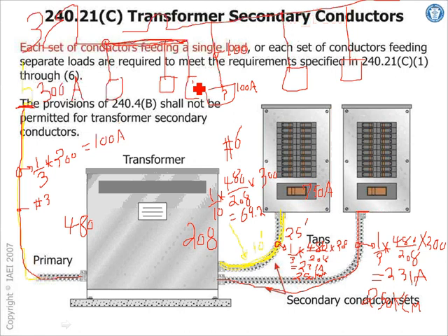All these, as an engineer, a lot of engineers don't like the tap rules. The tap rules compromise the integrity of the power system. Every time you tap a conductor, you compromise the integrity of the power system, right? But they're cheap and they work. So if your system reliability is not an issue, a manufacturer who's making shoes or whatever, they don't care too much about an interruption of the product. So that could be an easy fix for them.